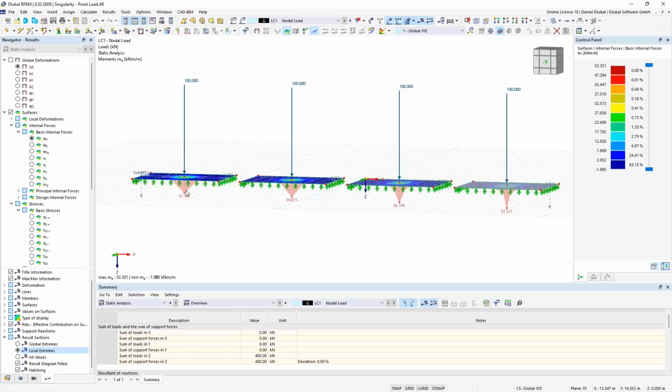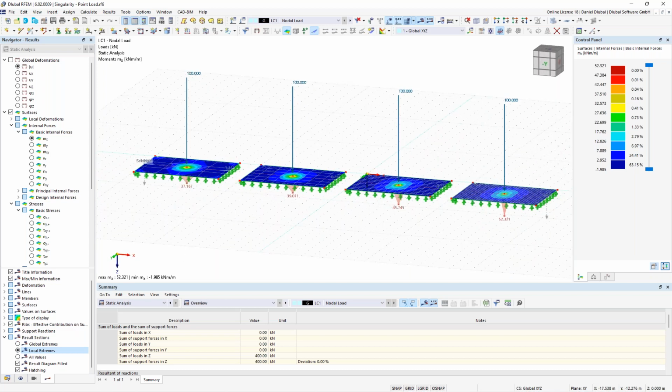On the left example, I have 37 kilonewton-meter as field moment, and on the right side 52. So we have different FE meshes, and from the former example we know that when I have a finer FE mesh refinement, the results are mostly better than with a rough one.